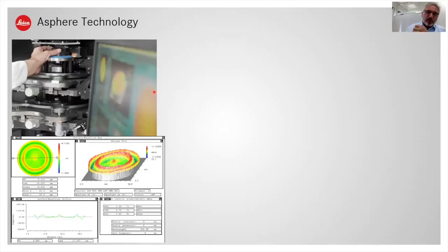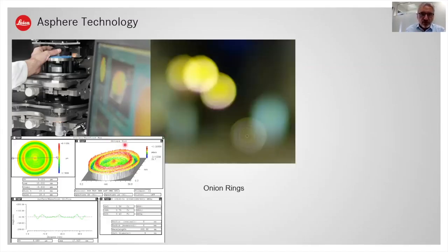And as we were pioneers in implementing Aspheres within high performance lenses, we learned a lot, and we failed a lot. We do the fine polishing technology not to get best performance in terms of MTF, but to get best performance in terms of bokeh. Because if you use the normal polishing technology, you have some irregularities on the Asphere, shown here as rings.